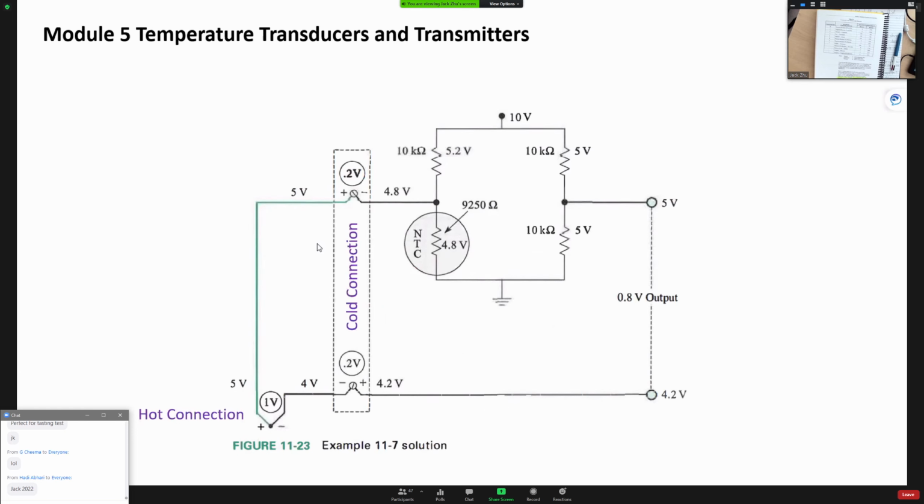If you don't pay attention to those, nobody can help you. For the thermocouple, they will have something called cold junction compensation. The purpose of that is to make your temperature measurement more accurate, because you use this junction to make the measurement, and you have a cold junction compensation to make sure the temperature is measured very accurately.